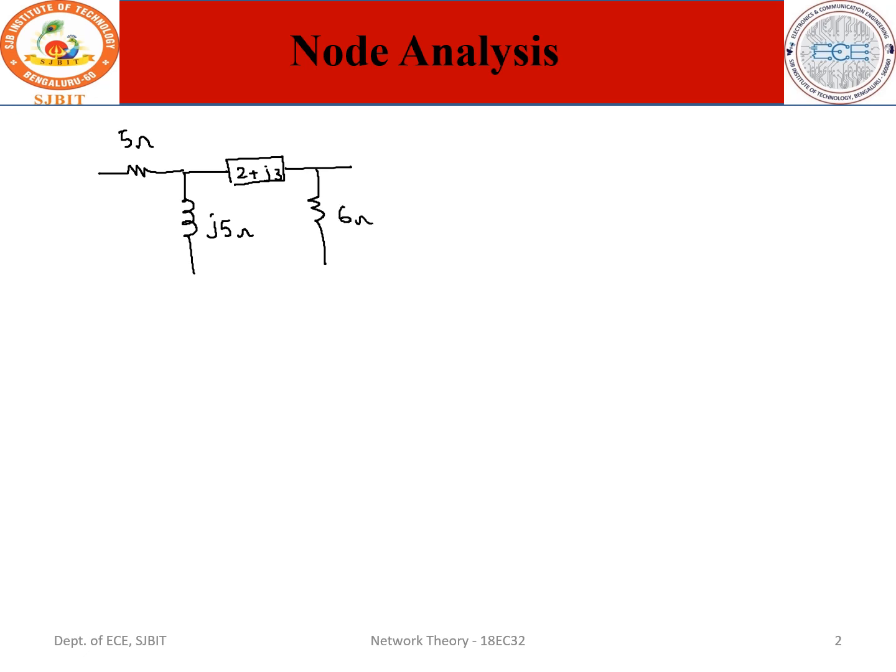Here this is a resistance, it is 6 ohm, and this is your 4 ohm, and this is Vx, and then this is 30 at an angle of 0 degree. So they can ask the question like this: use the nodal analysis to find the value of Vx in the circuit shown in the figure such that current through 2 plus J3 ohm impedance is 0.